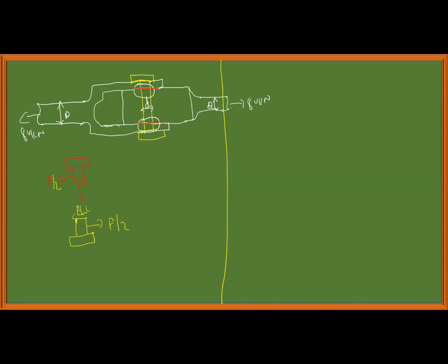But what you should understand is, since two areas are formed in single shear, we wrote that tau is equal to F by A. Whereas in double shear, there are two areas which are going to share, this area and this area. Generally, the author said tau is equal to F by 2A.